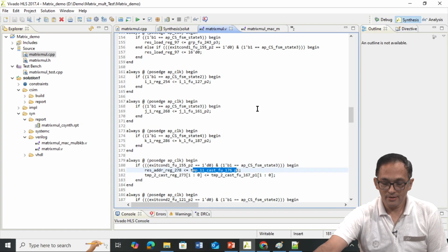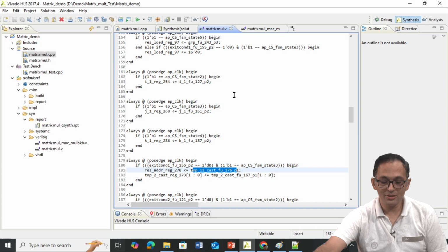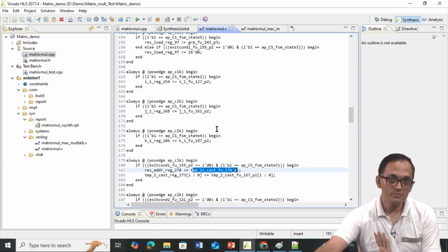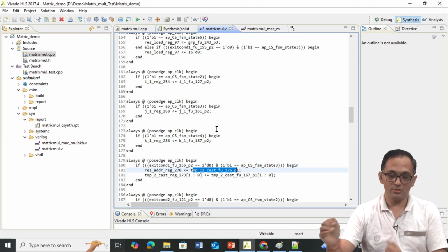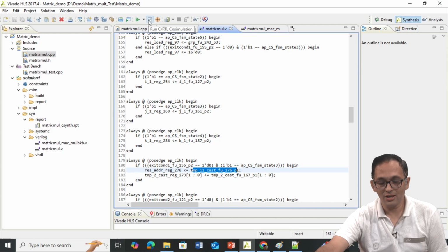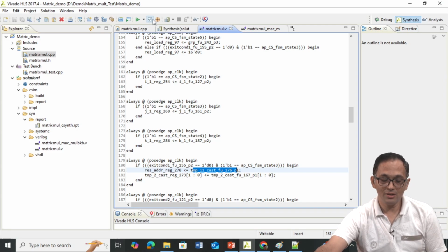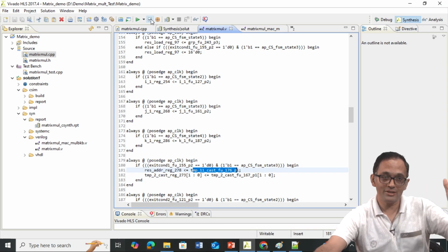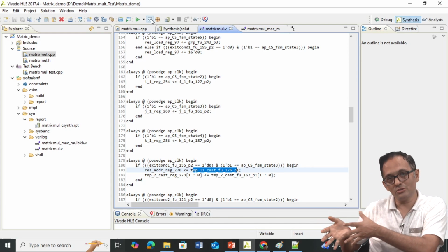So, this is how the entire behavior is getting executed. Okay. So, once you are done with understanding this Verilog, we also have to make sure that this Verilog generated by HLS is correct. Okay. There may be some bug in the HLS tool, and as a result the code may be wrong, right. How do you check that? You have this, the run RTL co-simulation. This basically says that you will run the Verilog with the same test bench you have written for C. So, it will take the same interface, convert that test bench into an equivalent interface corresponding to the Verilog.